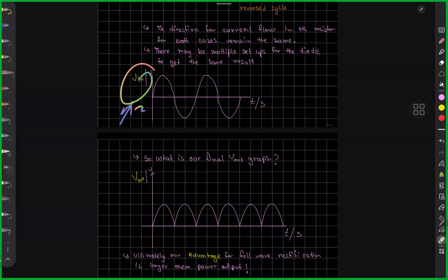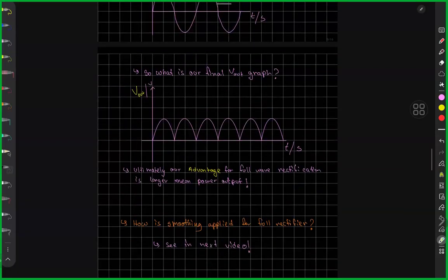Okay, this is the voltage in, right? This is the voltage in, that is positive, negative, positive, negative. And when rectified, it is all positive. And it's very interesting to me how this works, or how clever the setup is. So the advantage is a larger power output. If you have all of the wave of the current in one direction, obviously, if you take the average of this now, it is a larger average of power. Very simple. Make sense? Good.